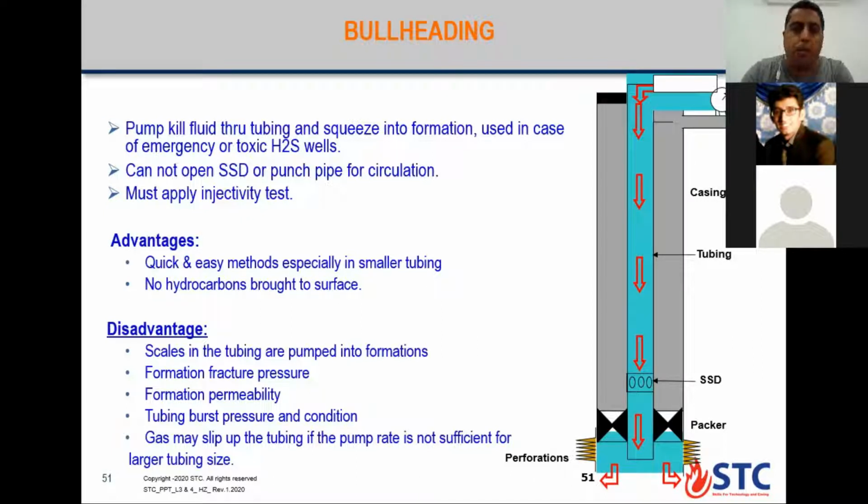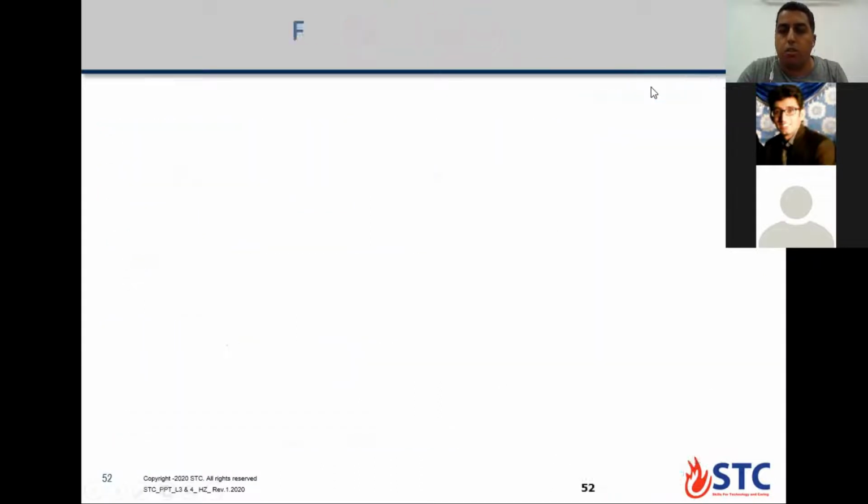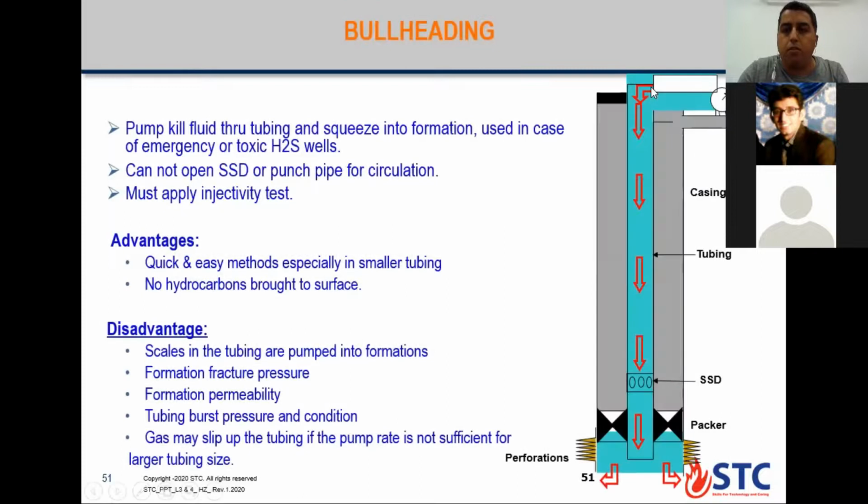Okay, fine. Thank you. Mr. Ahmed, I know the rules for injectivity tests, but if the formation is not taking any intake, like the injectivity of the formation is very bad, then what should we do? You will not be able to bullhead. You will circulate.